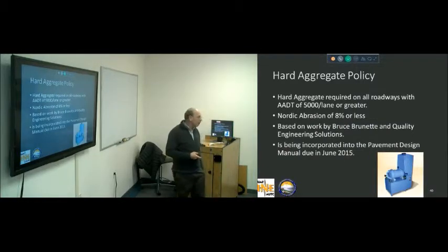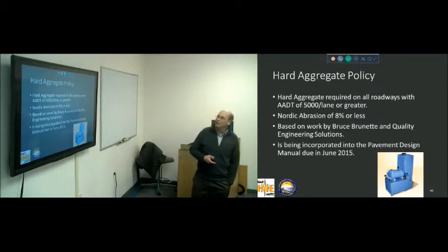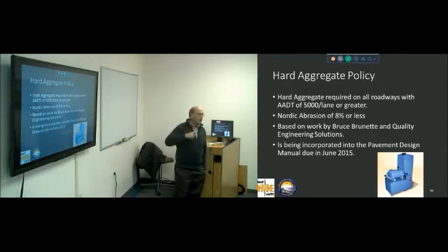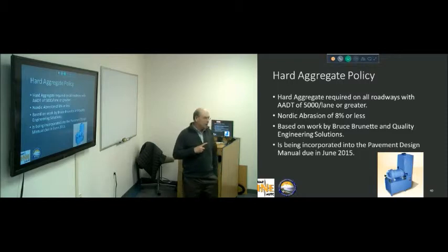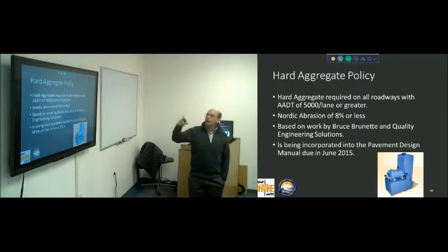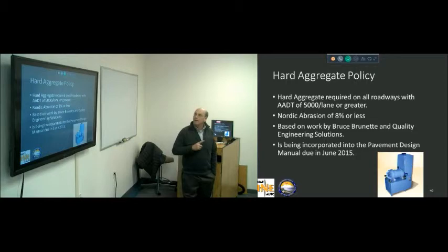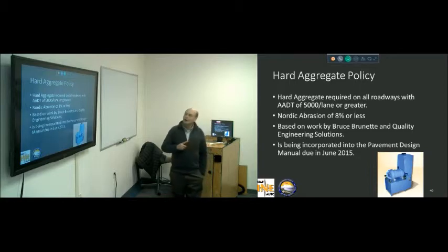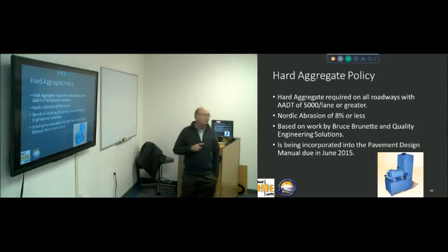There's a new hard aggregate policy that's coming in there, and Steve Sabullion and I and Mike Santangelo are going to be working on this into the new pavement design manual, the updated pavement design manual, which will be coming out here by June. Hard aggregate will be used on all roadways of 5,000 ADT or greater. There's something called Nordic abrasion, which is readily available. There's a picture of it there in the lower right corner. 8% or less. If you go to Scandinavia, 7% or less.